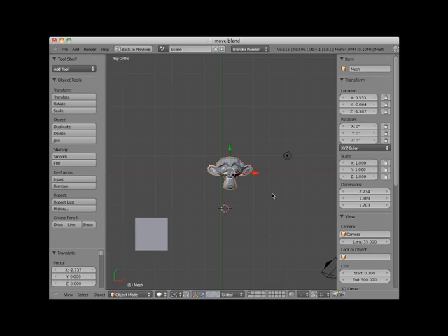Notice that I can also select the monkey object, press the G key followed by the X key, and move the object one Blender unit at a time by clicking on the up and down arrow buttons on my keyboard. I will left-click to stop the translation.